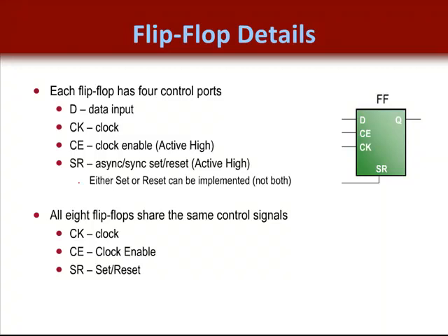The set reset port can also be implemented as asynchronous, although this is not as flexible. An asynchronous set or reset port cannot be implemented as a LUT input, so your synthesis tool and the implementation tools don't have the ability to map this control signal to a LUT input if it's asynchronous. You should always remember that clocks and asynchronous set resets always get access to the control ports. This is because they cannot be implemented otherwise. Specifically, asynchronous sets resets cannot be implemented as a LUT input, but synchronous set resets can. Now we'll talk more about this and its benefits a little later on.